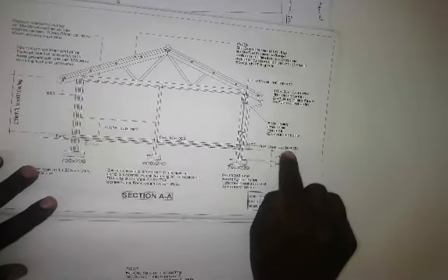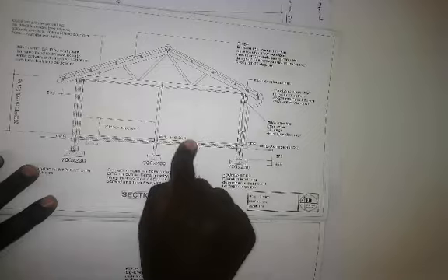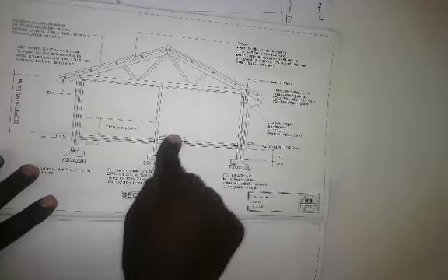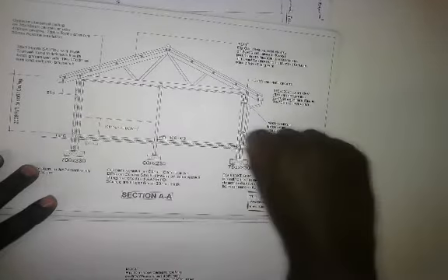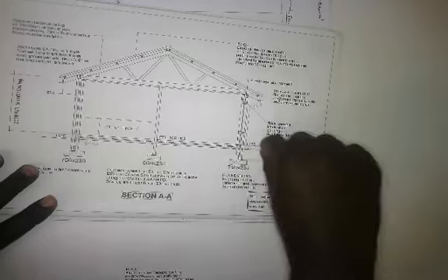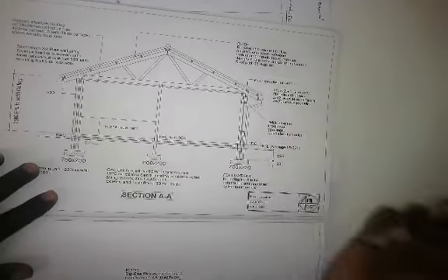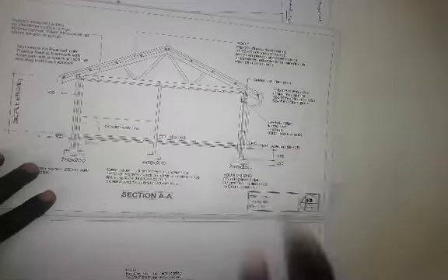So don't be intimidated when you look at levels and think that it's something to be scared about. So maybe this gives you a better view. So that's a level 99625. That's a level, and then here's this one 100,000. So that's a level. This level, deduct this, you'll get the difference, the height over here, finished floor level to ground level.